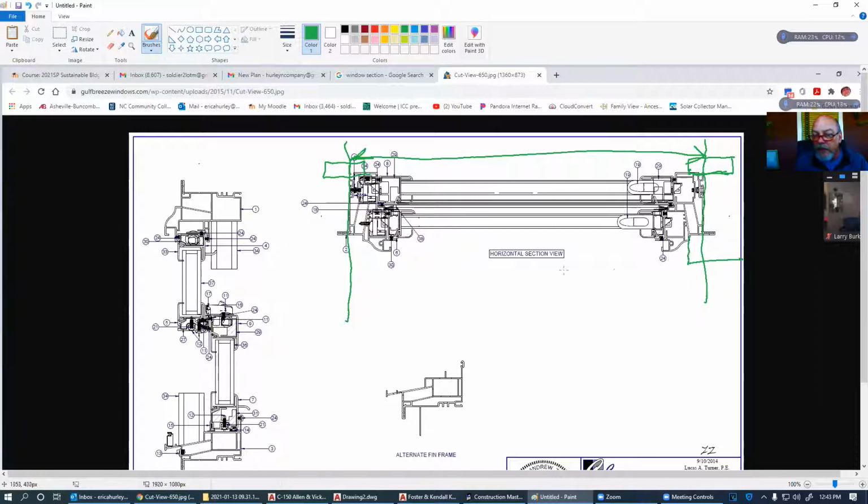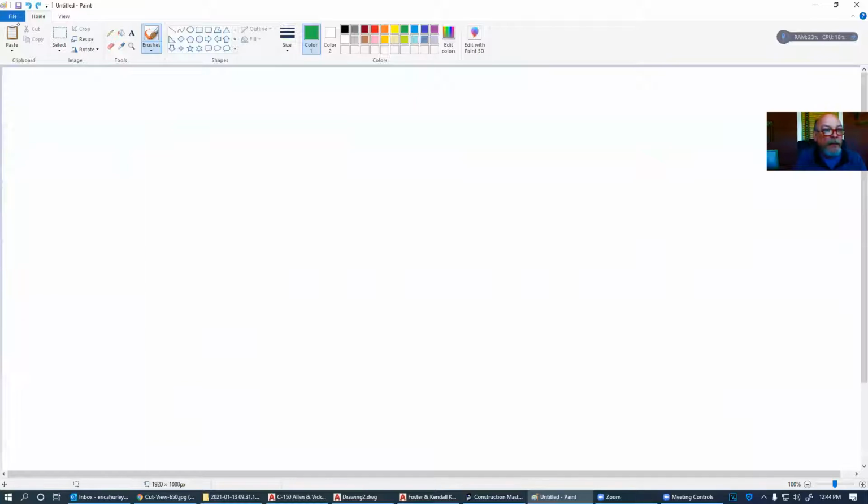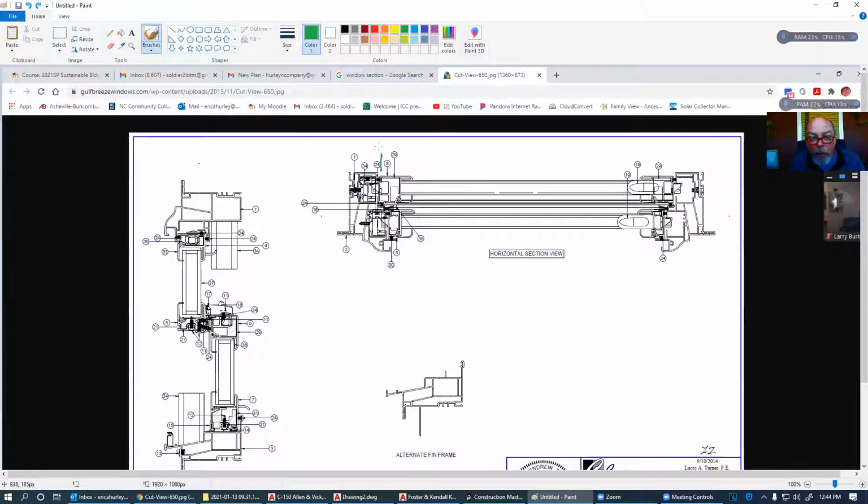The outside may be a little different from the inside, but use both as your best sense. If nothing else, measure your sashes and add 2 inches. In other words, what opens and closes, which is this point here, measure this and then add 1 inch to it on either side. That's probably pretty close to what you're going to have there in most cases. So that'll help you out.